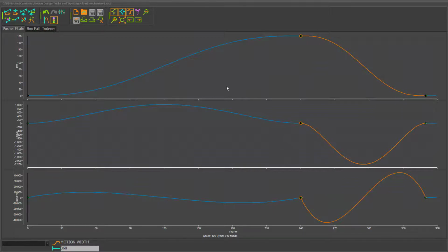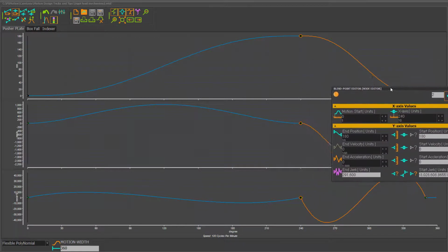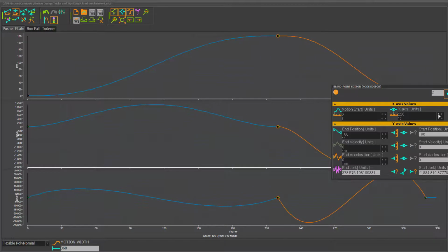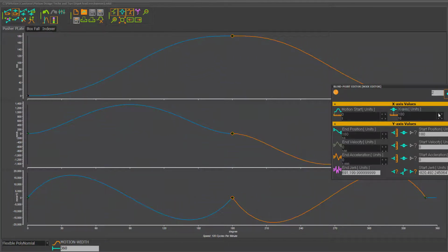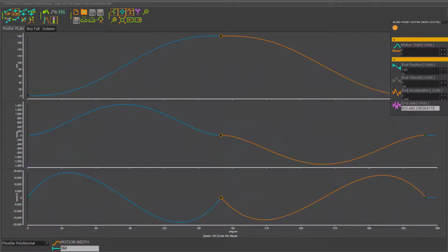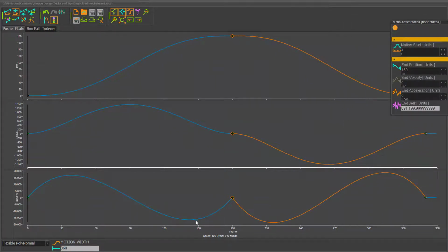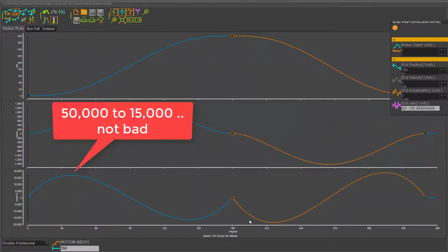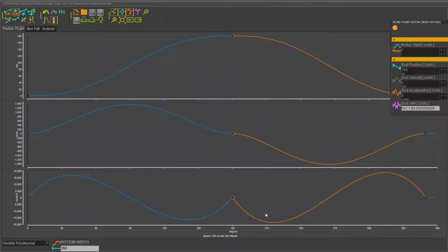So I'm going to do that, and then we'll have a look and see what the implications are on the model. So I'll go to the node editor, and I'll move this node now right the way across to balance the acceleration. You can see the accelerations and the velocities are now evening up. So we've reduced the maximum amplitude of the acceleration, which is a good thing, because, as we know, that will reduce the forces and torques that have to be sustained by components in the machine.